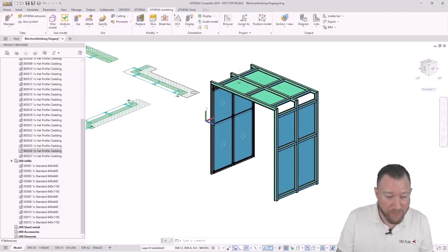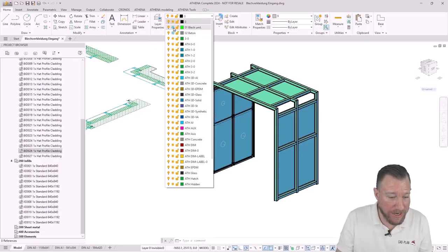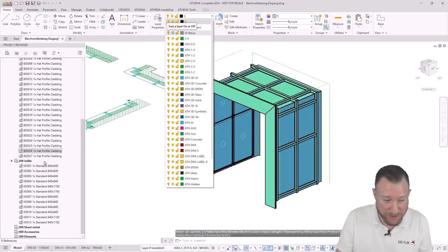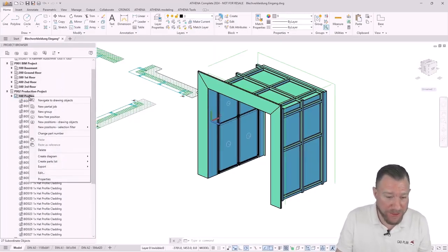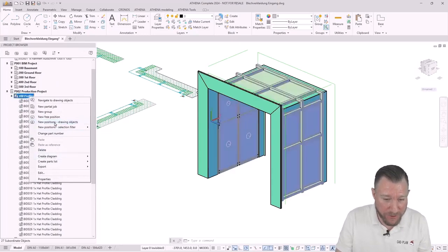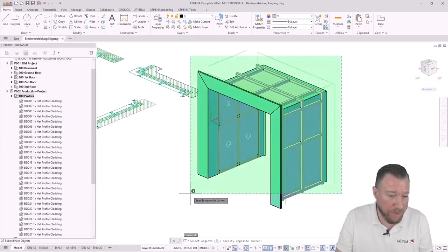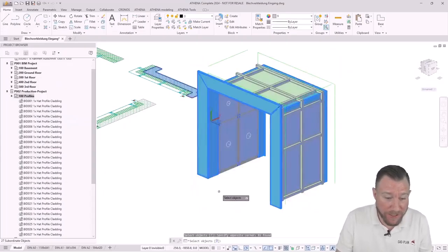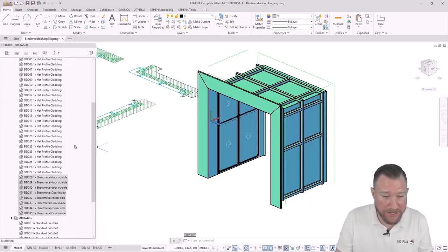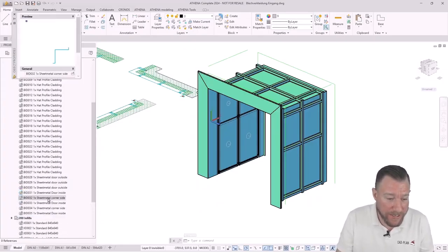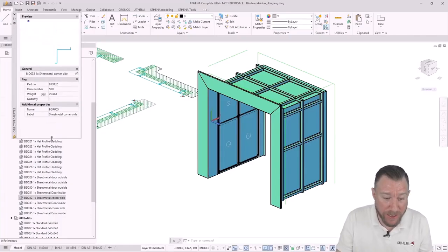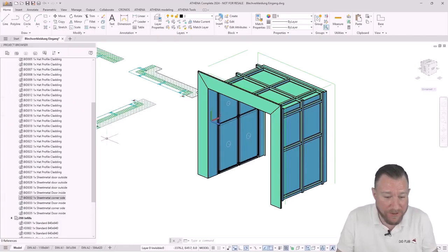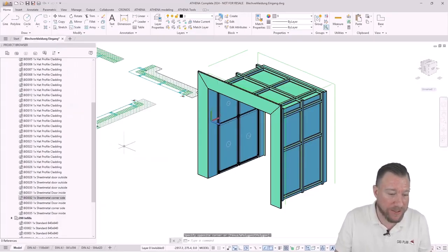Everything is registered. However, we would also like to include the remaining parts in the evaluation. So now the sheet metal objects are also positioned at the front and back of the entrance and the corner panels. You can of course access the properties of each individual part at any time so that you can quickly provide information in the later manufacturing process, or if parts are damaged later on the construction site.